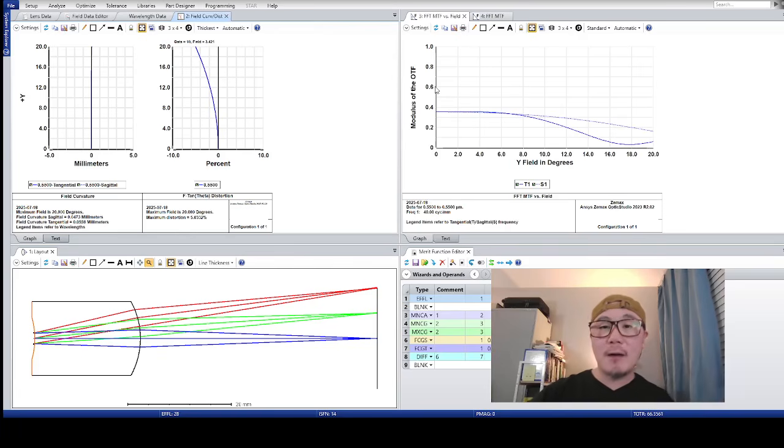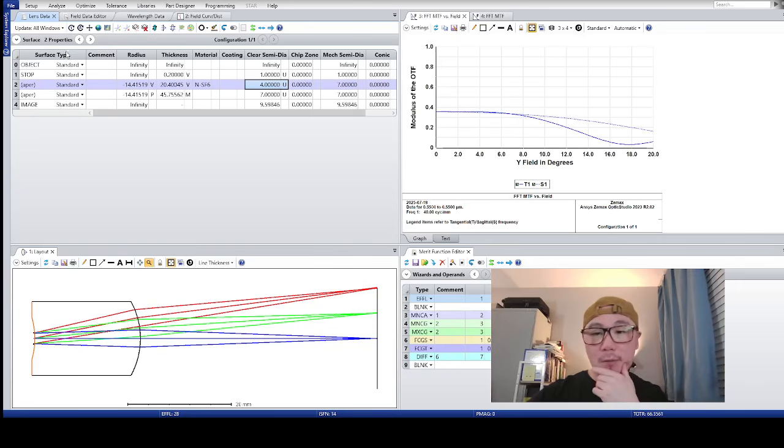So now I'm going to show you how to increase this MTF with slight aspherizing, because it's all about just spherical aberration. Now it's no longer about the field curvature. I mean, it's sort of, but not really. So let's aspherize. Let's go to even asphere.